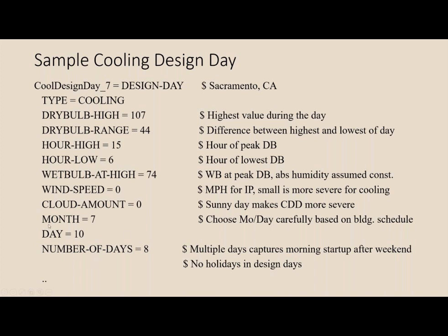Another factor is the month and the day and the number of days. I mentioned earlier that the design day schedules now have the ability to handle weekends as different schedules than weekdays, so you can get that Monday morning startup. In order to get that Monday morning startup, you also need your design day period to include the weekend. One way to be sure that happens is to set it to 8 days, so you know it's going to be a whole week plus a day, and you're sure you'll have at least one day after the weekend.